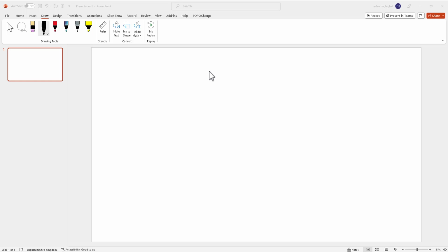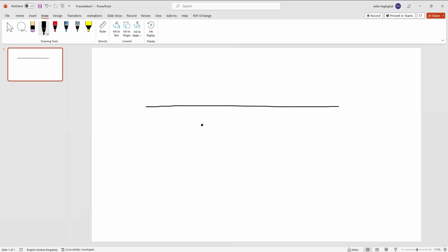In this part, we want to simulate a pipe mixing three different fluids with different temperatures together inside SolidWorks. So we start here, and there is a first pipe, second, and the third one. This is the main pipe, and there is a flow inside this pipe with a velocity equal to 2 meters per second.